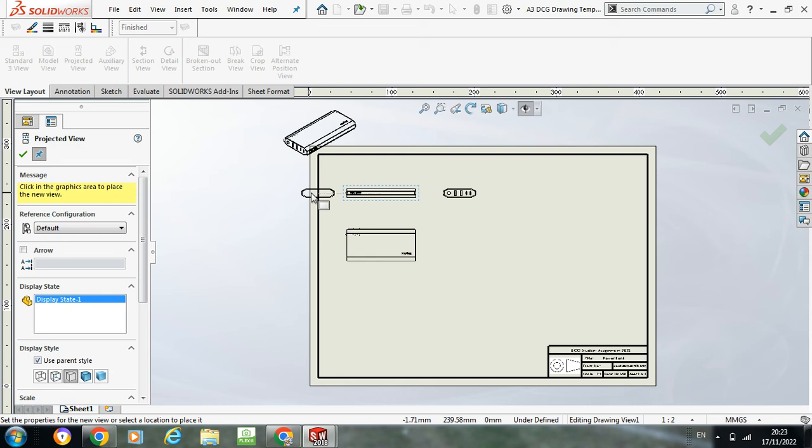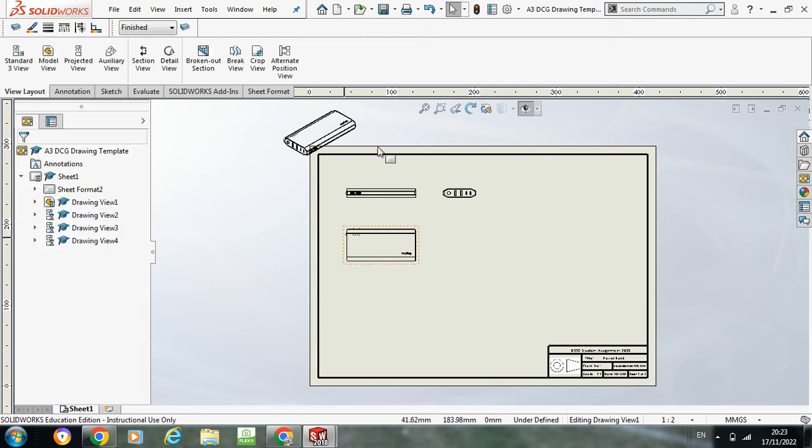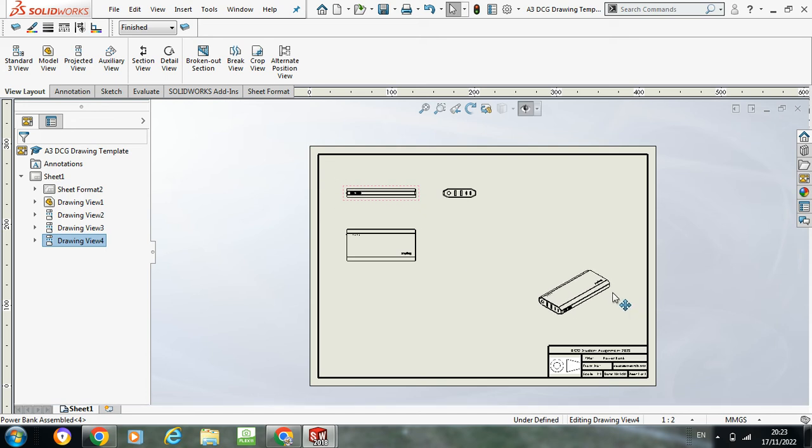Okay. The other way, if I went this way, that would show the other opposite side, maybe the back side of it, okay? But that's enough views there for my kind of orthographic views and obviously my isometric. So what I would then do is press escape. At the top left of your keyboard, press escape. And there we have it. Now, what I'm going to do is I'm going to take this one here in isolation, grab it with the little cross symbol there. I'm going to pull it down, put it anywhere on my sheet.